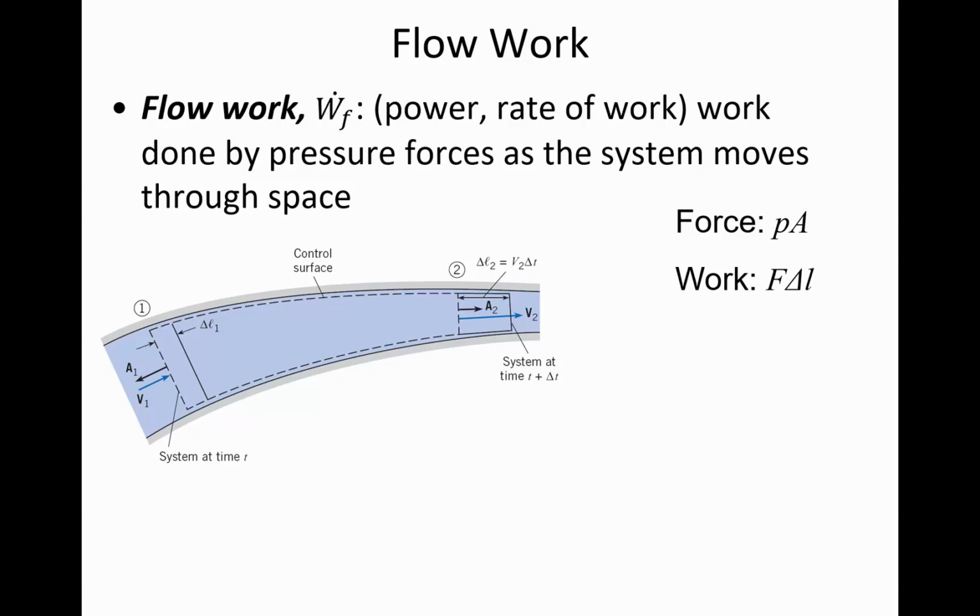Okay. When water's flowing through a pipe and the pressure is changing, then the water itself is doing work. If you remember in the momentum lesson, we said that if you cut a pipe where the fluid is pressurized, then the water on the outside of the control surface is pushing towards the inside of the control surface, and that pressure times area is acting as though it's an external force. And a force applied over a distance, that is work.